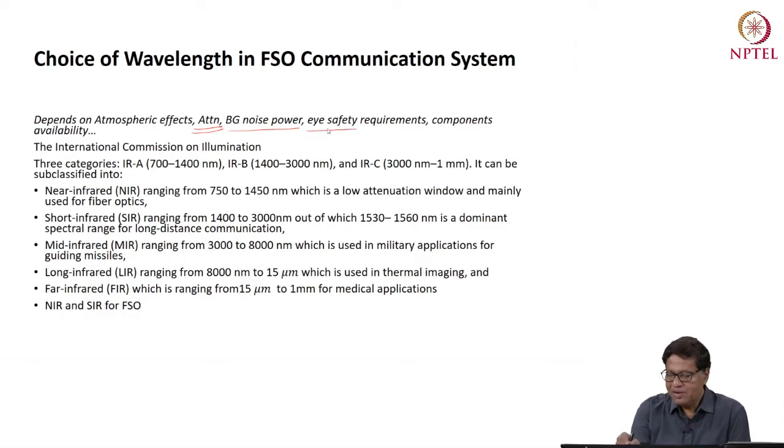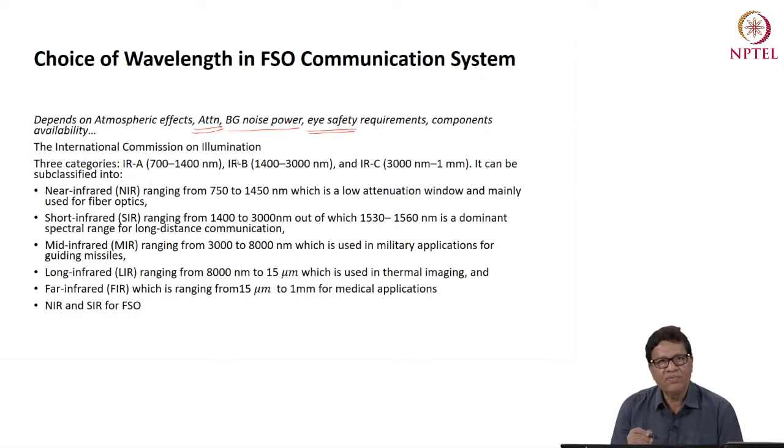And another factor which is important is eye safety, because not all wavelengths are eye safe. So there is a table defined which describes what power I can tolerate at which wavelength, what the maximum exposure limit is. All those things are defined in eye safety requirements. So you have to select a wavelength which is harmless to, for example, eyes or tissues.